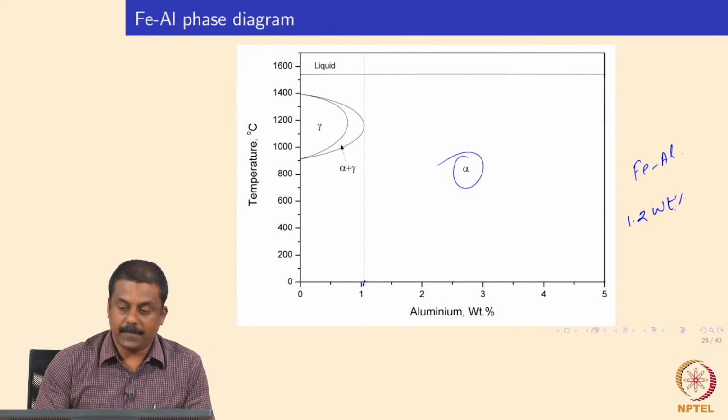even after cooling to room temperature. Because of that, we have a very soft microstructure in between a martensitic microstructure in the heat affected zone as well as in the rest of the fusion boundary, leading to strain partitioning when you are applying load.